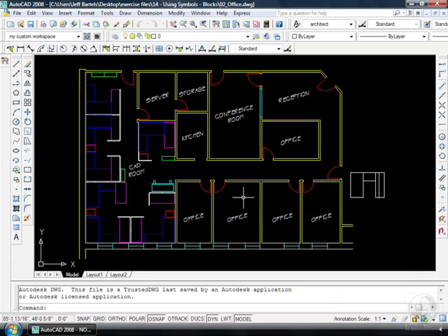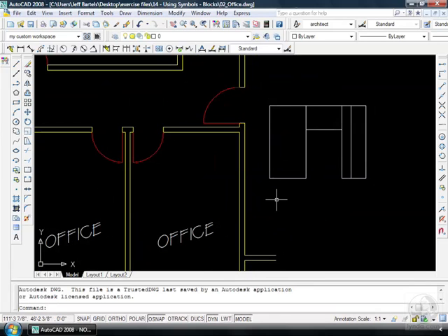That way if I want to insert a mainline desk into somebody's office, all I have to do is insert a block as opposed to copying geometry around on my screen. Now I've already created some of my furniture blocks, but I'm going to make another one right now. Let me zoom over to the right. This line work represents an executive desk, and this was drawn using the actual dimensions for this piece of furniture, so I know that the block that I'm creating is the actual size.